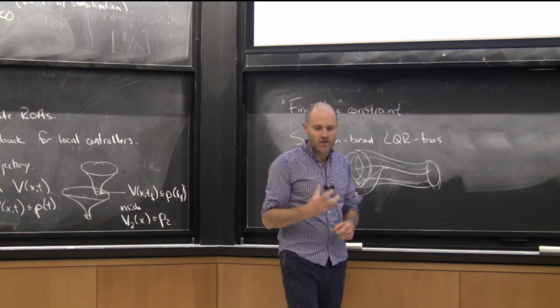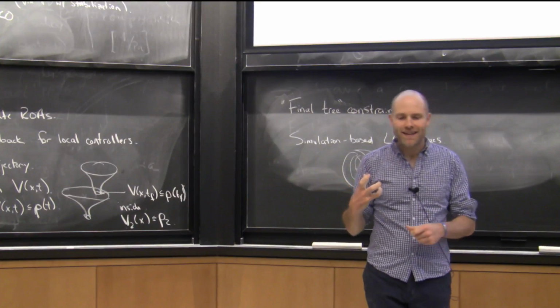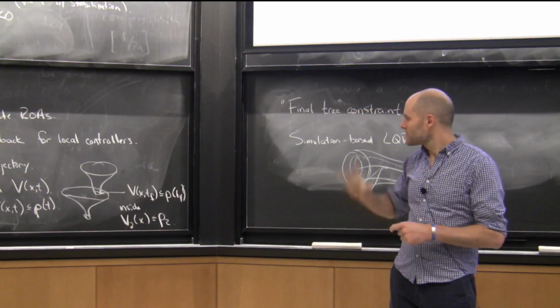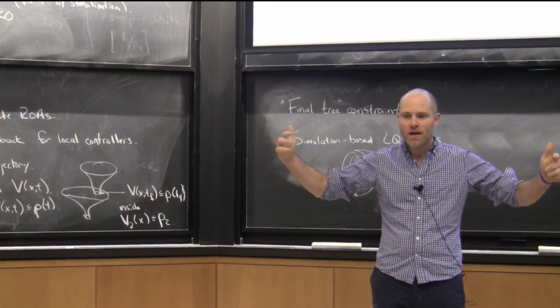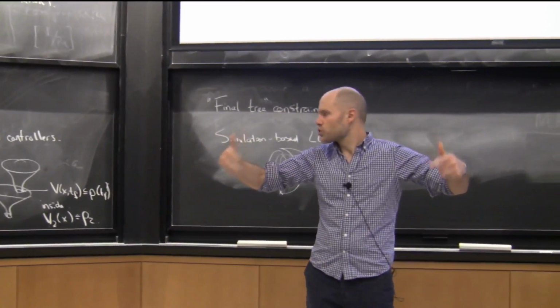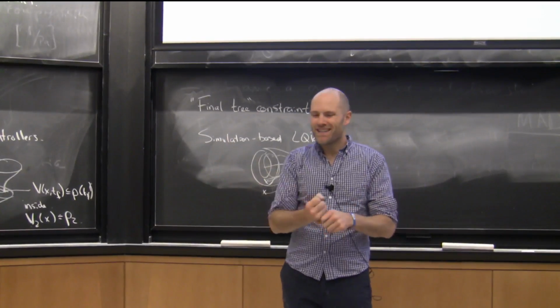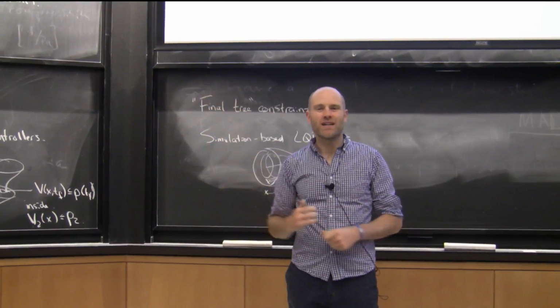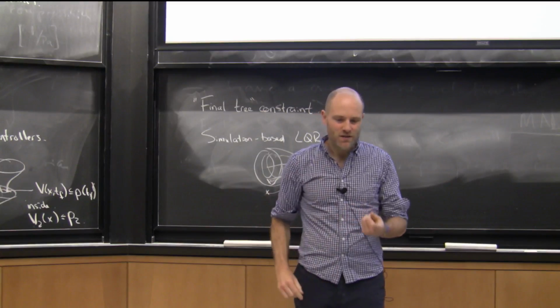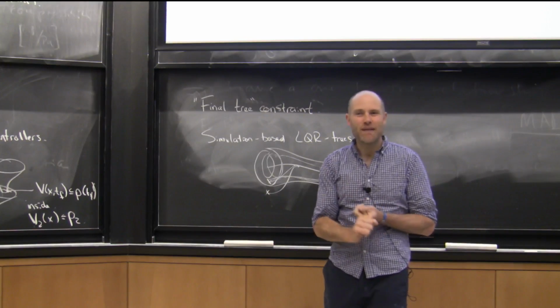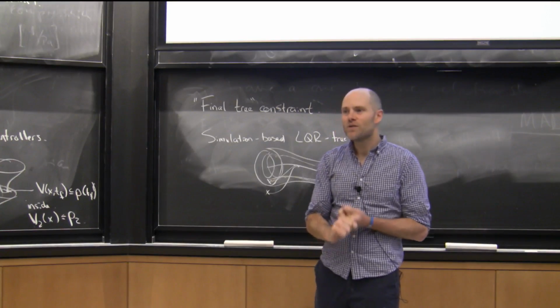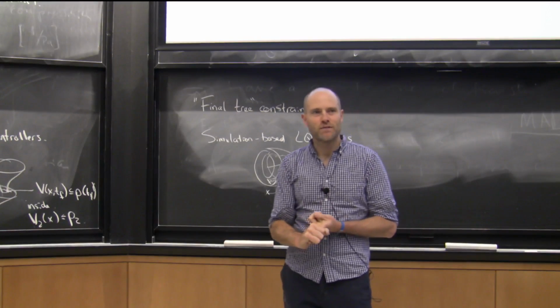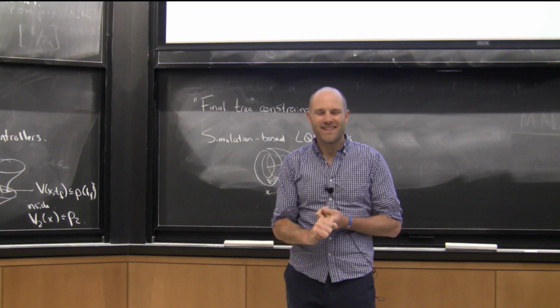once I have those, an automatic way to generate that, I'd like to be able to project into this. I think it's okay to have this notion of state space at design time, but the overall control techniques should not be wed to the trajectories too tightly, because then even if deciding which state I'm in requires full state feedback, that's also a gotcha. As soon as you have a dependency on full state feedback, it's bad.